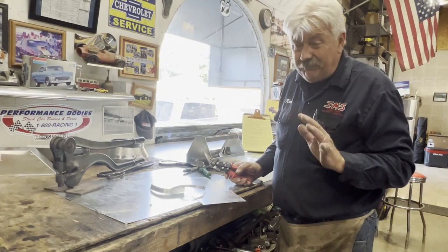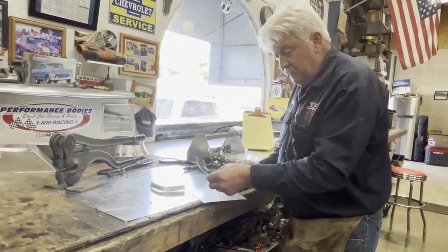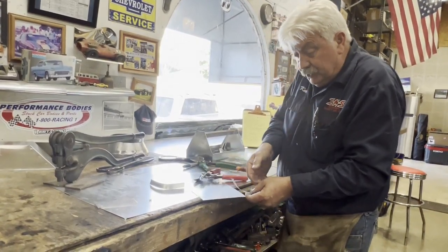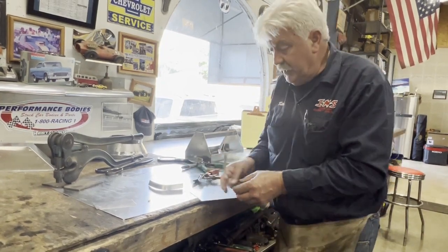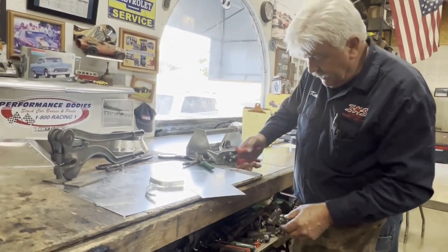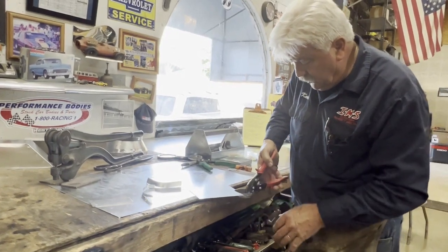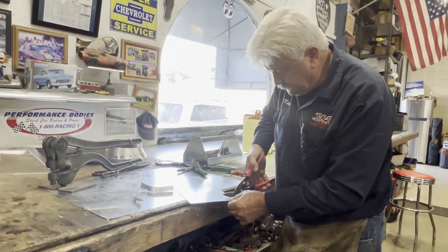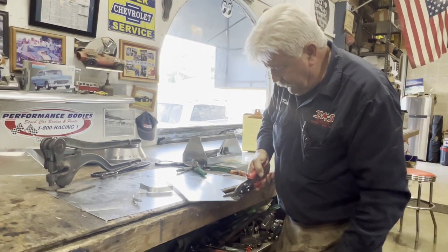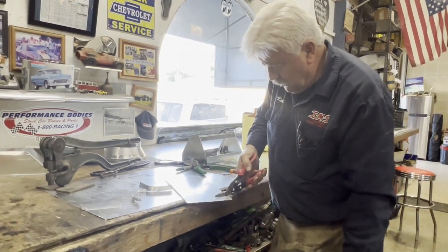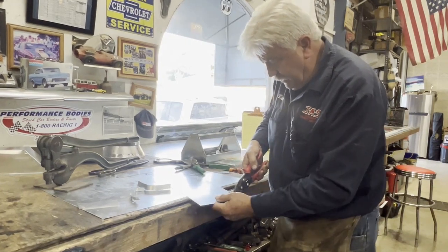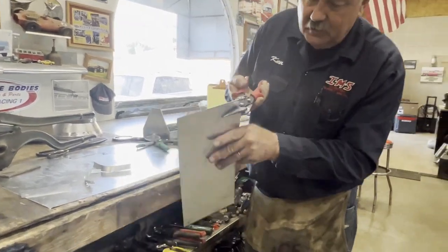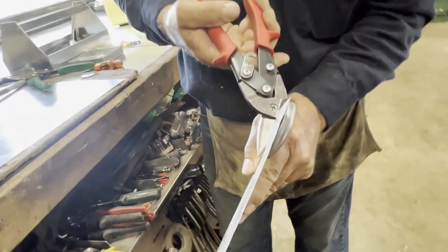The other roughly 15% is actually to spread the metal apart to allow you to continue that shearing function. So what I want you to do is anytime we're shearing, rather than let one hand do all the work of shearing and spreading, because we have to spread the metal to pass our snips through.